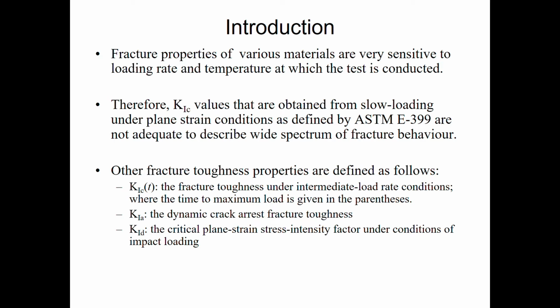Alright, for the introduction, fracture properties of various materials are very sensitive to loading rate and temperature at which the test is conducted. Therefore, K1C value, which is the fracture toughness that is obtained from slow loading under plane strain conditions, as defined by ASTM E399, is not adequate to describe the wide spectrum of fracture behavior. Other fracture toughness properties are defined as follows.